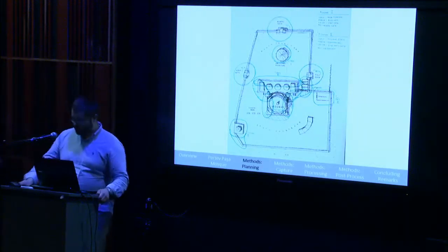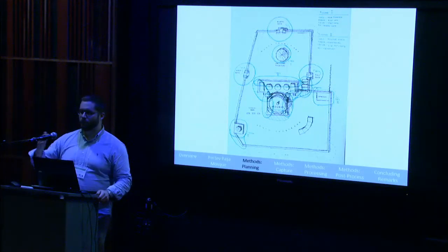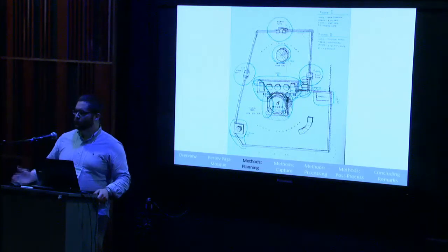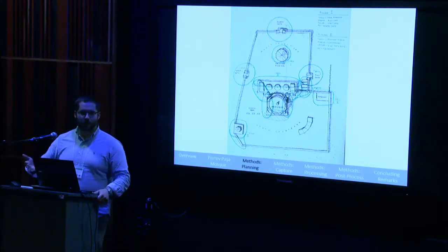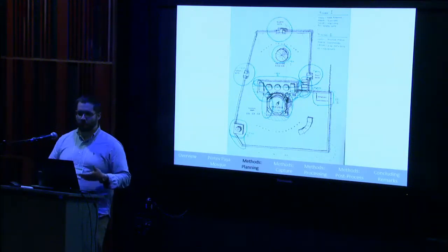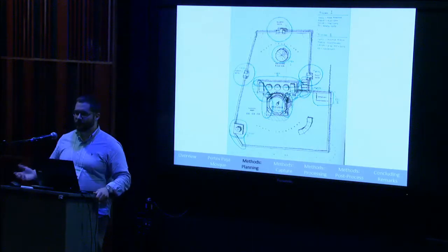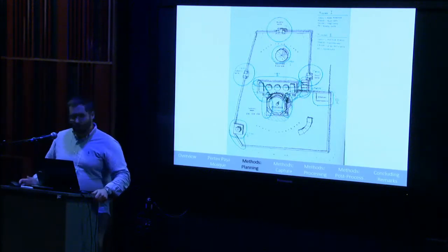Sure. So as we got into the photogrammetry process, we broke it down. One of the other goals while we were there was to teach the students a documentation method that they can take with them. So we had to achieve that from start to finish, including an example project within a week. Photogrammetry suited itself pretty well to that, whereas something like laser scanning is a lot more time intensive, both to capture and then process. So photogrammetry lent itself pretty well.